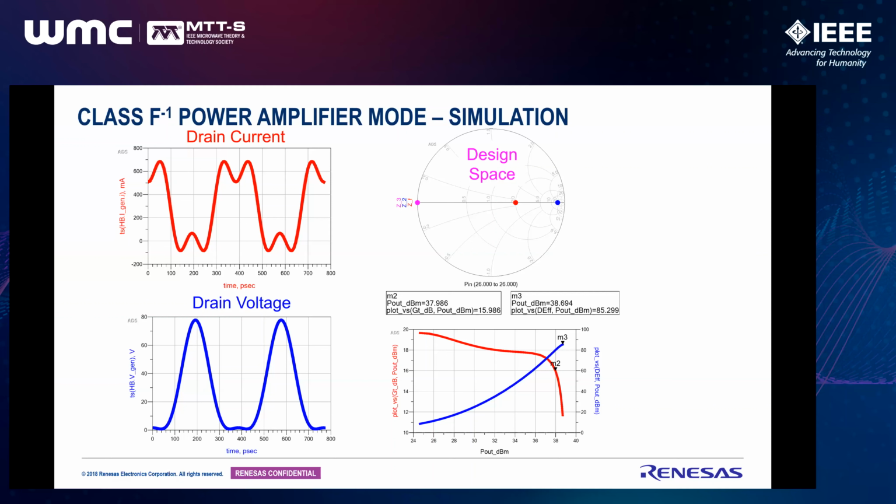So what I'm trying to show here is that all the theoretical calculation still holds very well as long as we are presenting the right impedance intrinsically to the device. And we can see that efficiency is up to 85% compared to the theoretical 91% of efficiency. Again, it's not exactly 90% or 91% efficiency as the theoretical computation because of the knee voltage of the device.